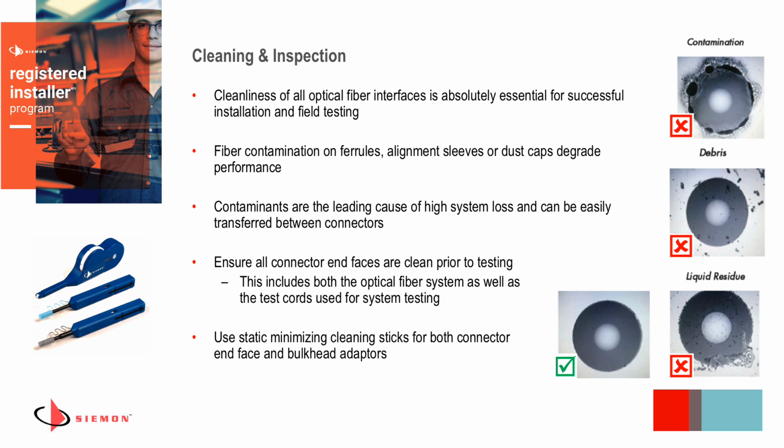And for example, cleaning an end face of a connector is one thing, but when you want to clean the end face of a connector that's behind an adapter plate, it's important to consider using cleaning sticks, which actually have the ability to clean both a regular fiber connector end face you might be holding in your hand, as well as clean the end face of a fiber that's already installed behind an adapter plate.